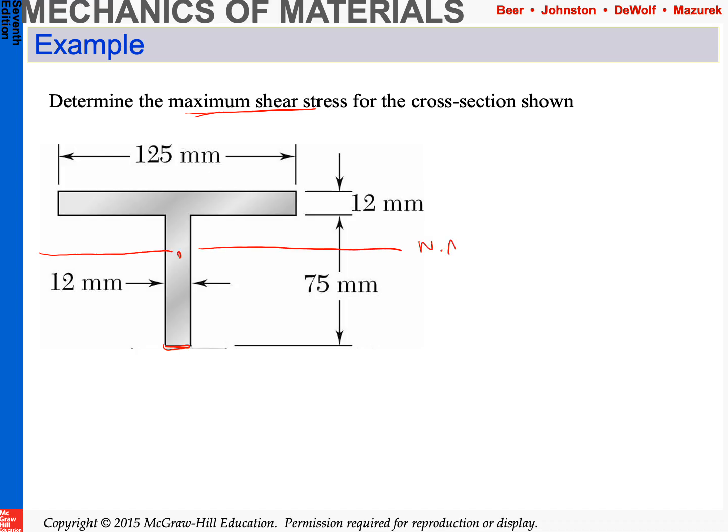So we have our neutral axis, and our shear stress has a distribution that is basically a parabola with the highest point at the neutral axis. And it also will depend on the thickness. So you may have here is very small and then it jumps sort of like that. So in this particular case, again, you might have two different parts. For example,